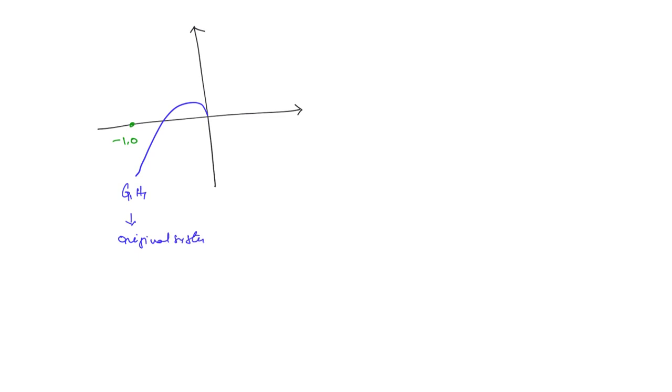Finally, one last point is, how do you find the critical time delay? That means if you have a function which is much stable, okay, about point minus 1 comma 0 is here and G1 H1 is like this. This is the initial system or the original system. Now you are inducing a time delay of, let us say, TD. Then it is going to be shifted like this. Okay. If you include another furthermore time delay, then it is going to be at the verge of instability. Okay. So this is TD1, this is TD2, let us say.